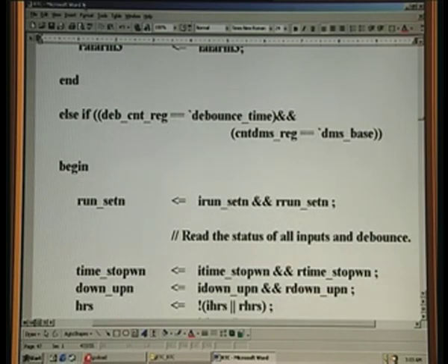And if that is not satisfied, next it may satisfy this condition. This condition is debounce counter equal to debounce time. So that is, debounce time is 3 millisecond, we have seen. So when it is 3 millisecond, what action should we take? This is not only reckoned with this, but also we see with reference to a decimillisecond also.